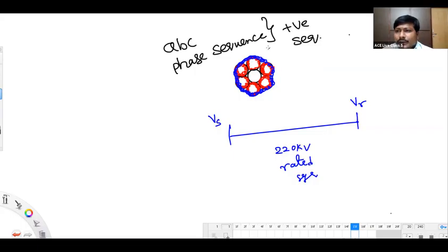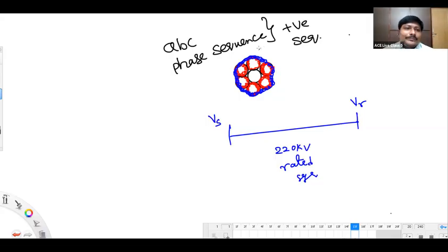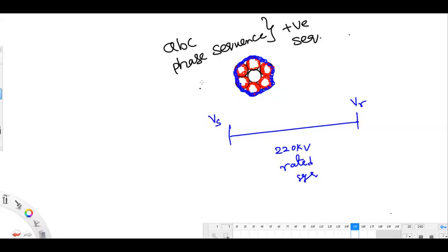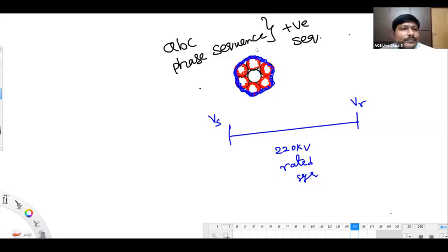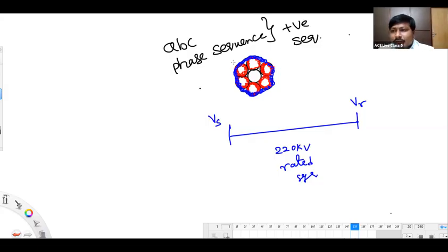You are reducing the radius of the conductor to skin depth, not by skin depth. So you make a very thin conductor. Then its current rating will be very low, no, sir? Then you have to bunch a number of strands together to make up the required current rating.